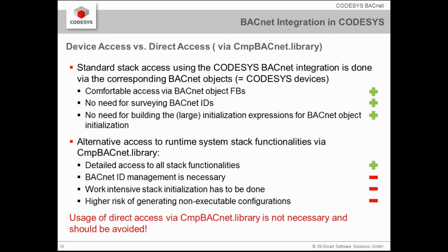object initialization. There's also another way to access the external stack in the runtime system, and this is via the component library CmpBACnet library. The advantage of using this access is that you really have detailed access to all stack functionalities.